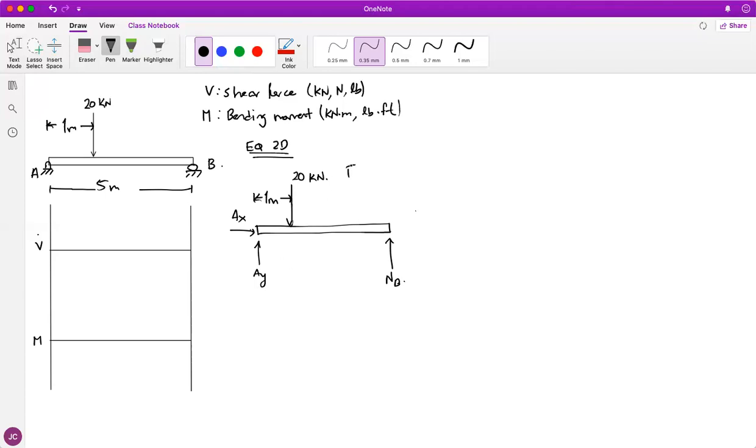So this is your free body diagram, okay? This is a typical thing to do when you're working in statics. Now that you have that, let's work out the equations. I'm going to start with the x part. The sum of forces at x gives AX equals 0. Let's go for y. For the y part, I have AY going up, the normal going up, and this 20 is going down, so it could be a minus 20. But I'm going to put it on the right-hand side of the equation, as a positive 20.